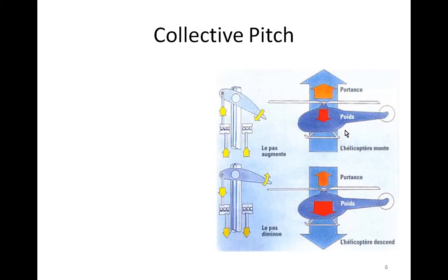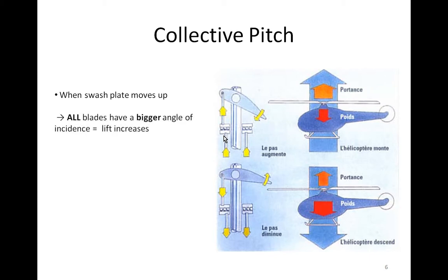We will see on this figure. When the swash plate moves up, pitch of all blades increases. Then lift increases. When lift is greater than the helicopter weight, then the heli moves up.